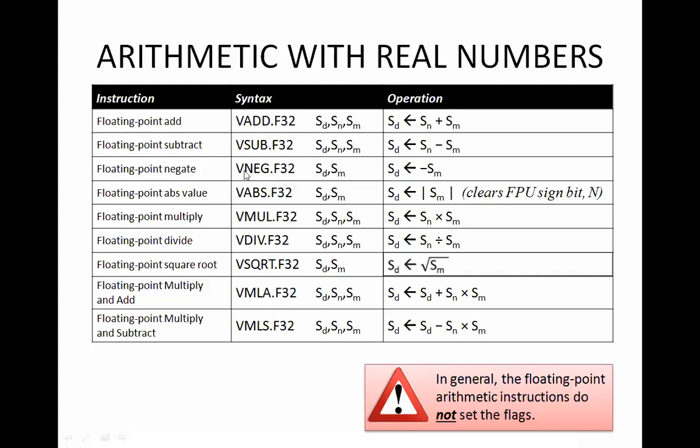Two operations are happening here, a special instruction: multiply and add. First N and M are multiplied, and whatever is in the destination is added, and the final destination is updated. So multiplication happens only between N and M, and addition happens to the product of N and M and SD. The final value will be updated in SD. Similarly, like addition, we have subtraction also. Multiplication remains the same, but it is subtracted from the SD value, and SD's final value is changed.